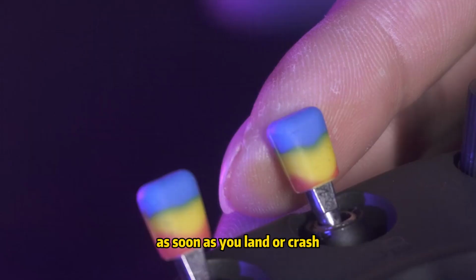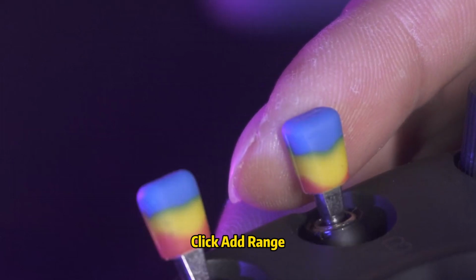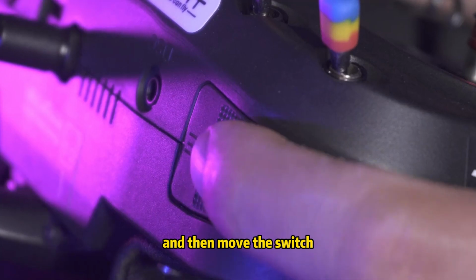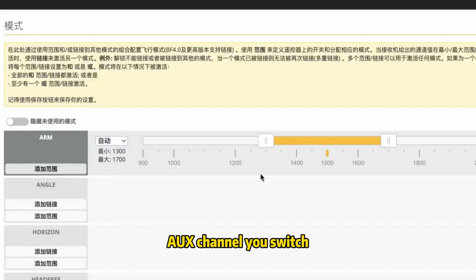And you should disarm as soon as you land or crash, and the motors should stop immediately. Click Add Range, select Auto Channel, and then move the switch that you want to set. It will pick up whichever AUX channel you switch.